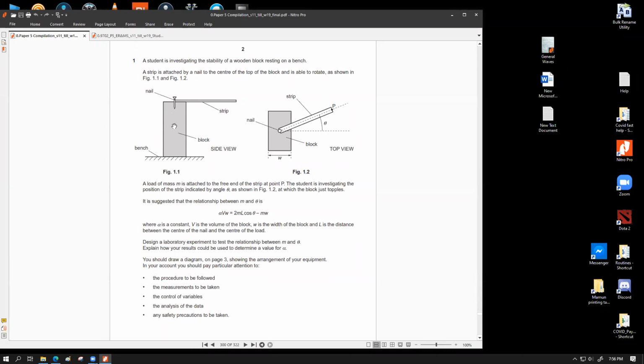So let's say for this surface, this is the side view. You take 1 measurement along this line and then another measurement along this side. And you do the same thing on the back reverse side as well. And as for the top view, you do 1 measurement close to this edge and another measurement close to this edge, and you also do that for the bottom side as well. So there are 4 faces where you can measure the W. You take 2 readings from each of the surfaces so that you can get a total of 8 readings.